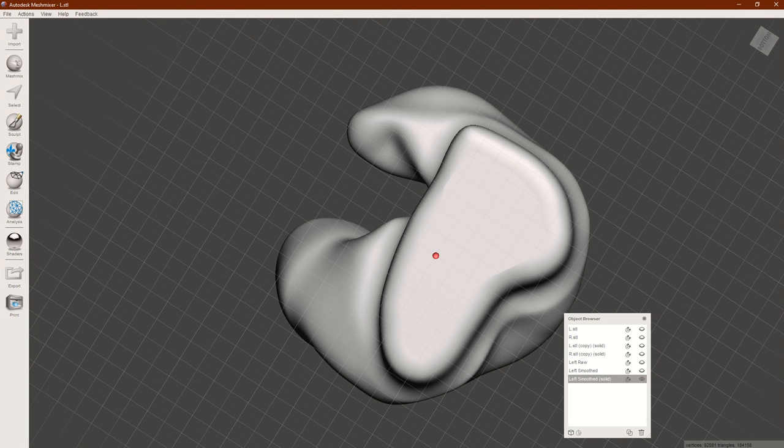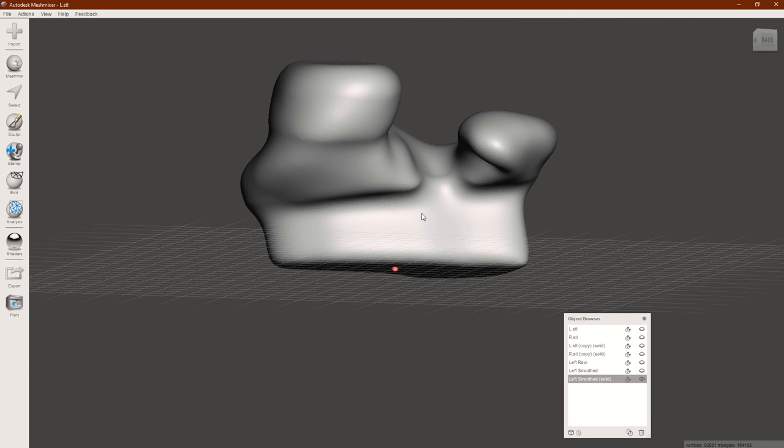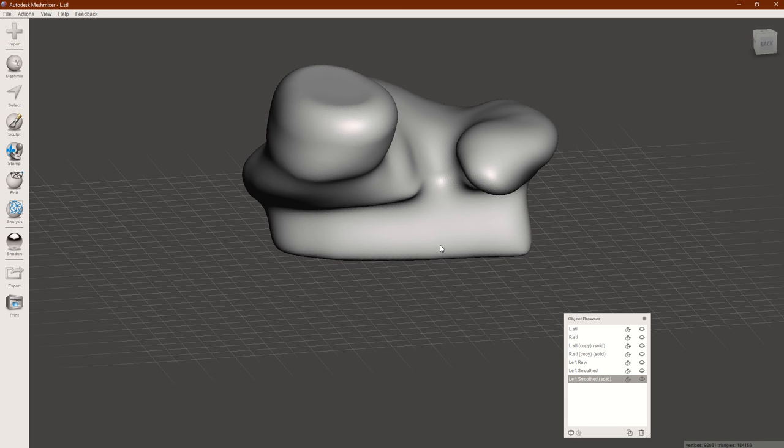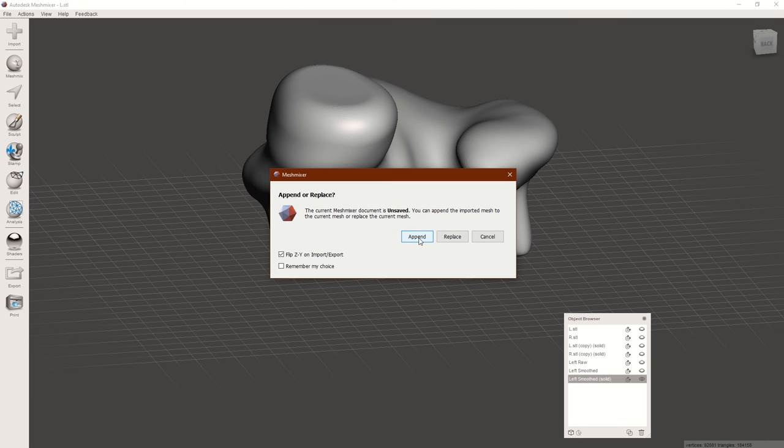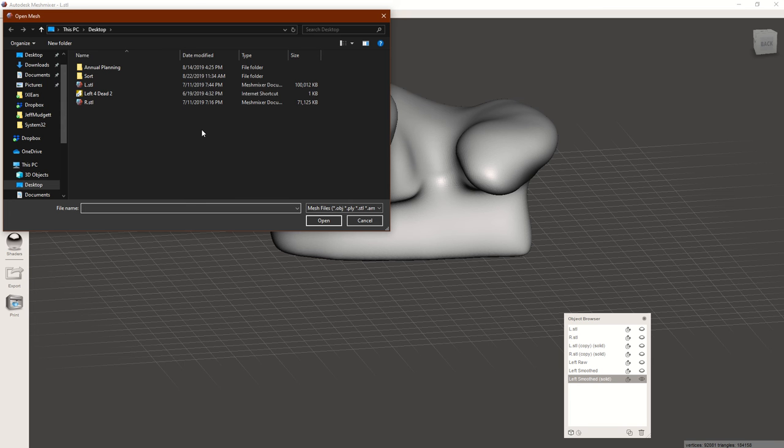Okay. So now that I've done this, I've basically smoothed that junction. I need to get ready to put in a connector for the cable. That's the next step. So what I've got here is I've used a micrometer to measure my particular MMCX connector. I'm going to import that. I've basically built it. I'm going to append.